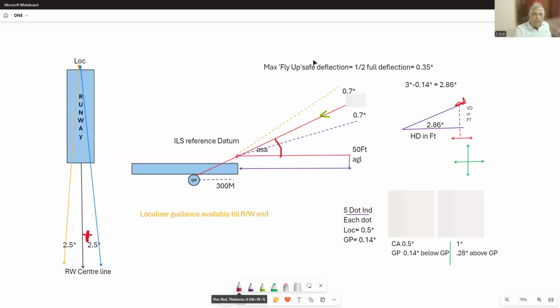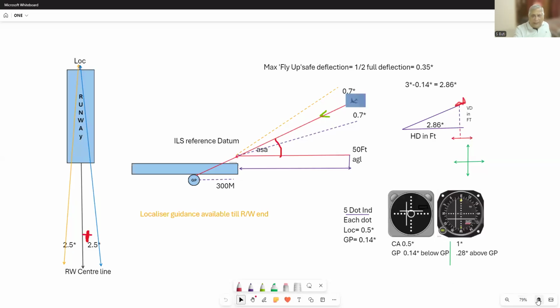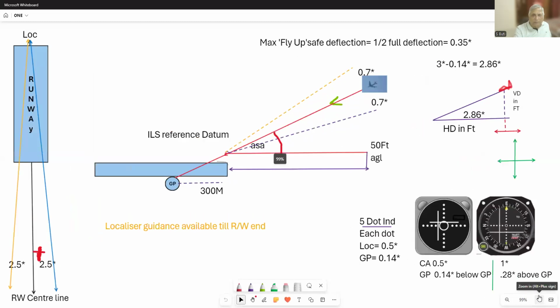As you know, this instrument helps you land in adverse weather when you visually possibly cannot see the runway, maybe the visibility is bad or there are low clouds, then you can carry out an instrument landing system. It has an ILS meter with two needles. One is a vertical needle called the localizer needle, and one is a horizontal needle called the glide slope or glide path needle.